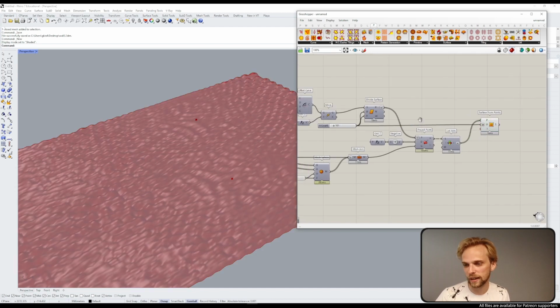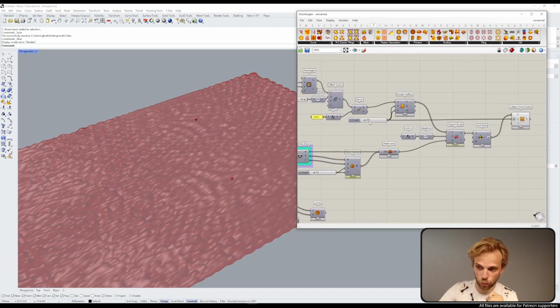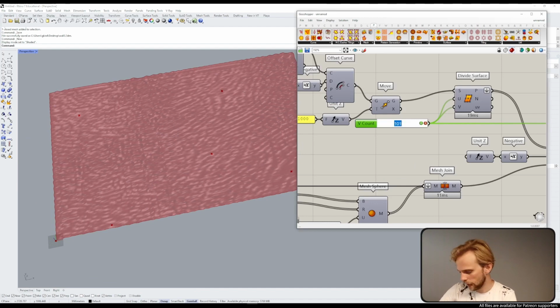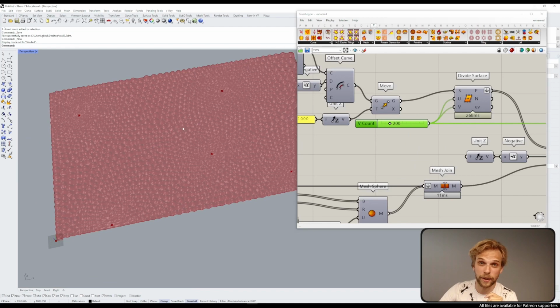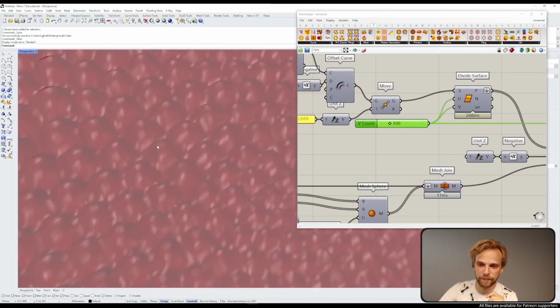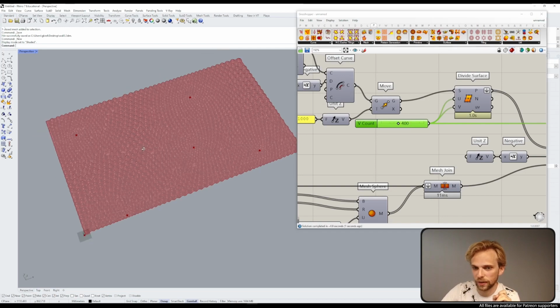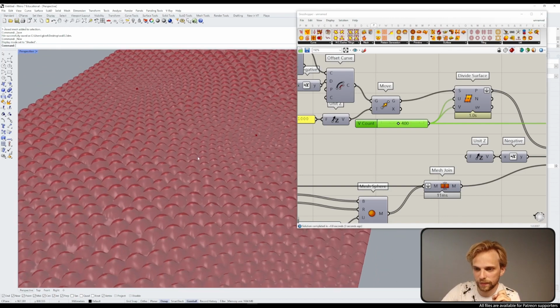The reason why it looks like garbage is because we have 101 vertices here, right? Or divisions. So it's not enough resolution. If we have 200, it's better, isn't it? It's much better. If we have 400, let's double that. 400, it takes much longer, but it's even sharper.